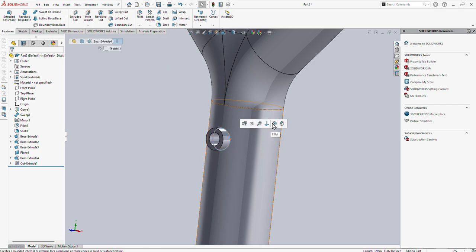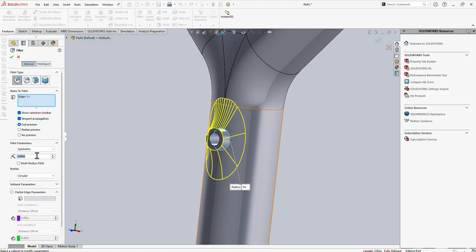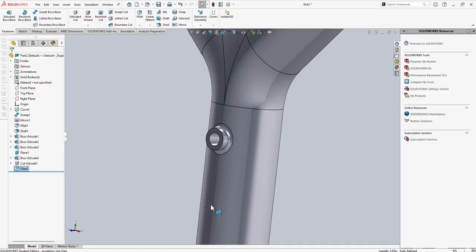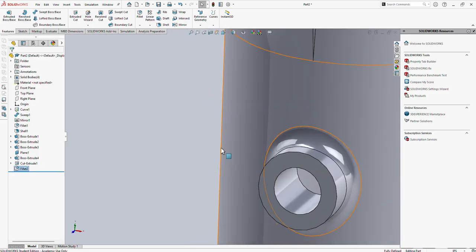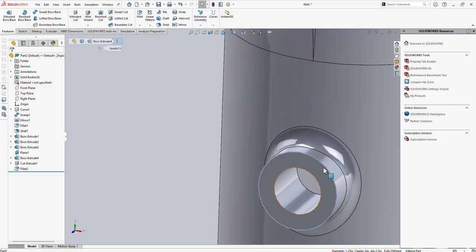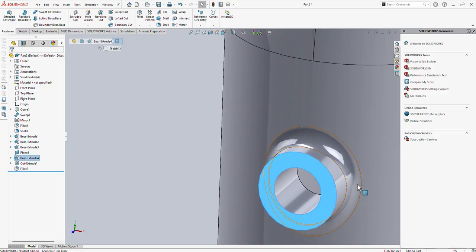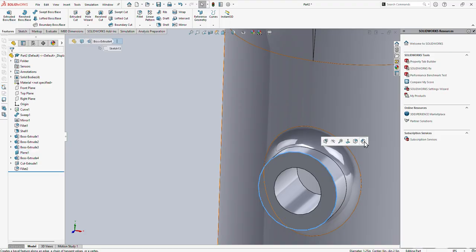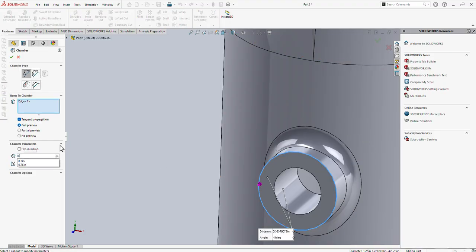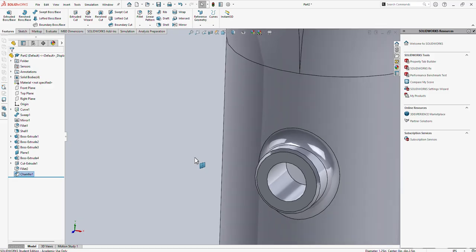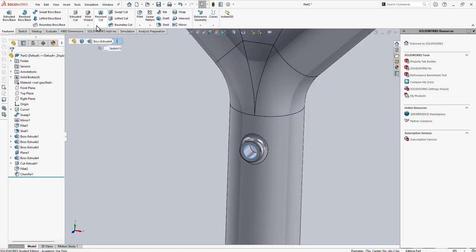Let's do some fillet over here so that we have a nice welding spot over there. So let's do it 0.25 inch. Okay, so chamfer the outer edge, sorry, select this, chamfer it 0.0625. Is it too much? Okay, 0.05. Okay, and let's select this edge and go to, sorry, yep, that's fine.